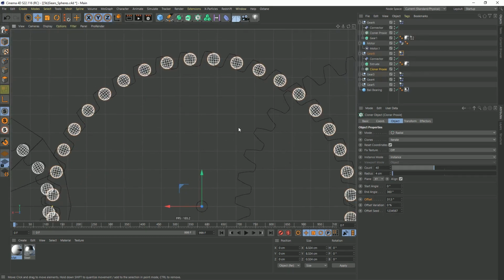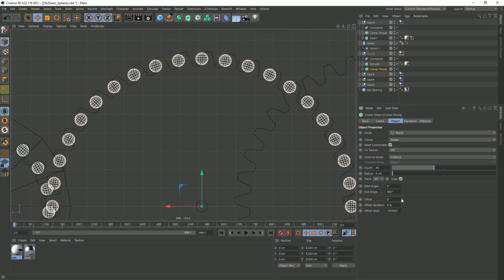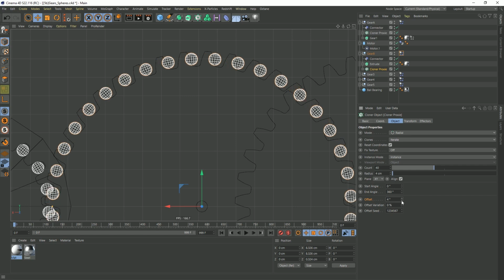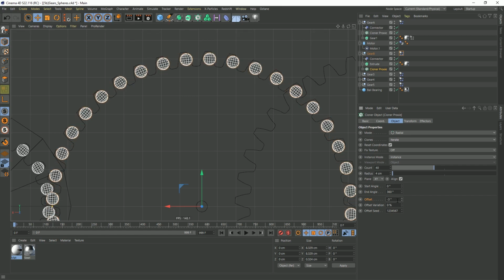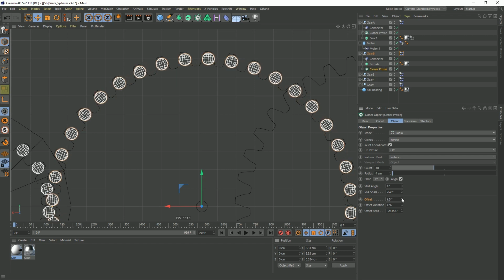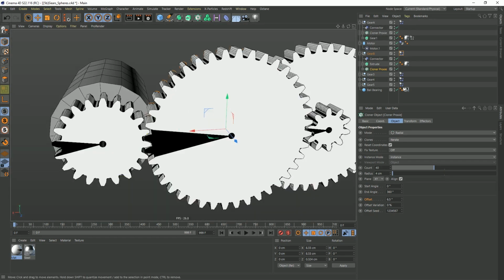It just needs the proper offset. So on the offset, I'll right click on the up and down to reset the 0 and just increase this number until they line up really well. You can also go negative if that's quicker to get there. And like I said, if you want a 0.5, we'd say 0.5 and then 0.5 and increase the number from there until hopefully you get one lining up pretty well. That's pretty close. So with those lining up, it's already filtering this information down really nicely.